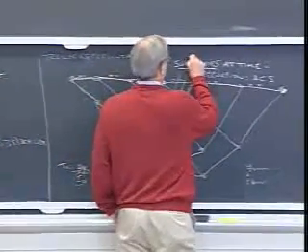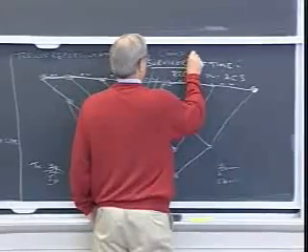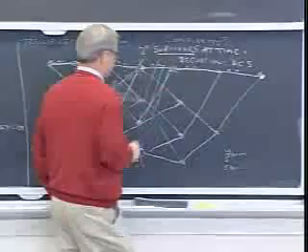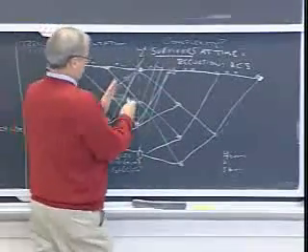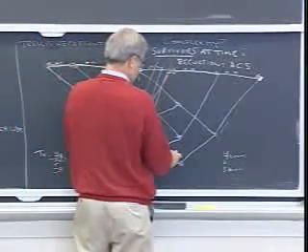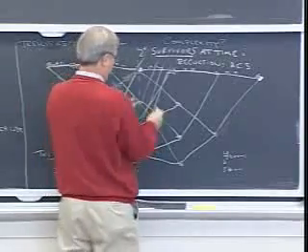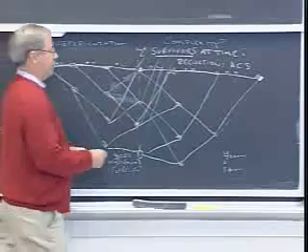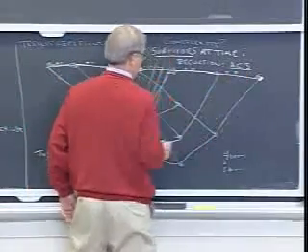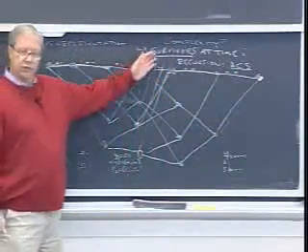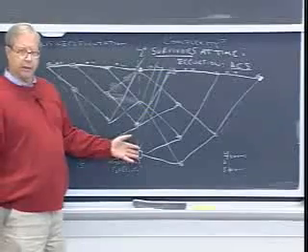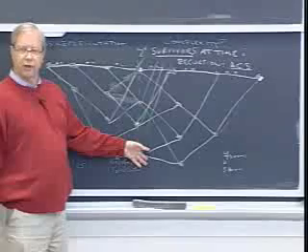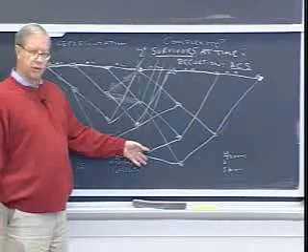What is the complexity? We always want to be talking about performance versus complexity. So it's a recursive algorithm. We do exactly the same operations every unit of time. What do the operations consist of? They consist of add, compare, select. How many additions do we have to make? The additions are basically equal to the number of branches in each unit of time in the trellis, which is 2 to the nu plus 1.